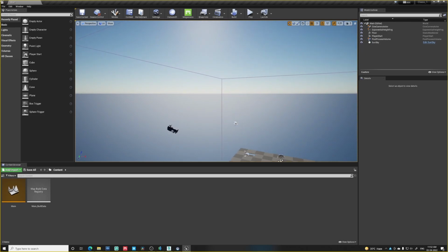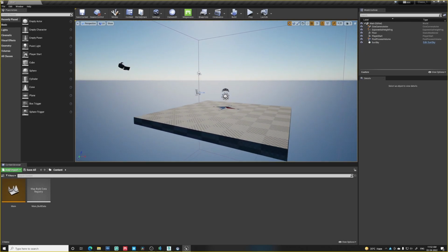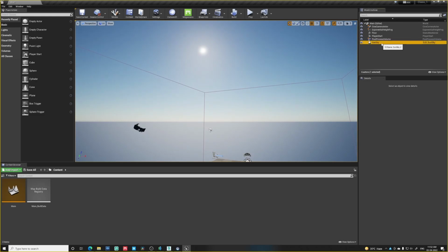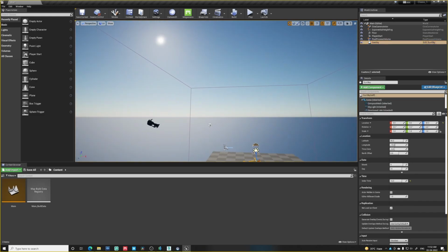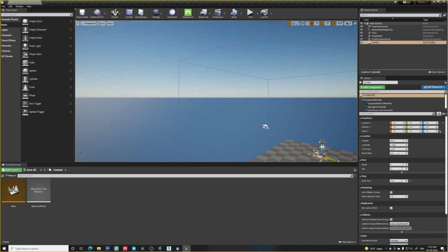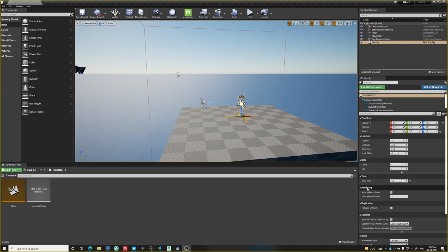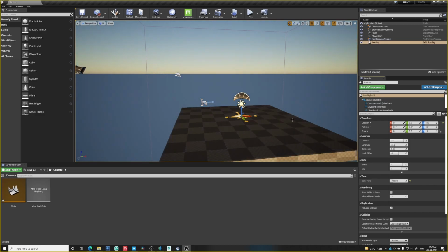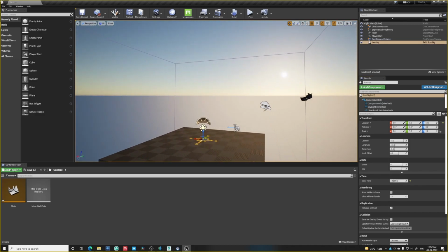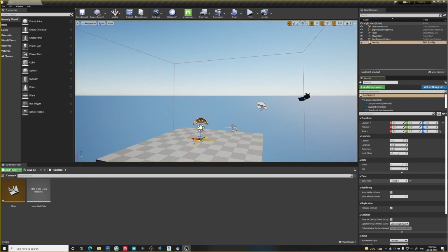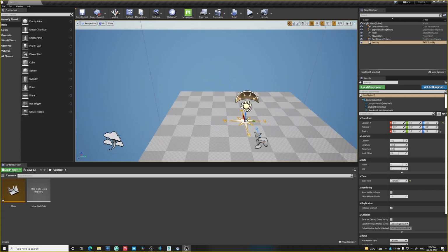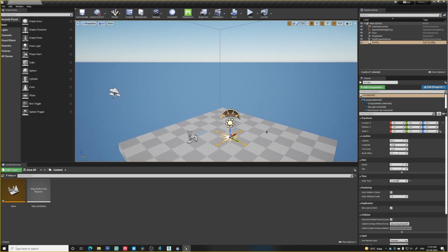So when you select this, we already selected this architectural template. This gives you a sun and sky. This sun and sky has this solar time, month, and day. If I change the solar time, it will change the lighting.